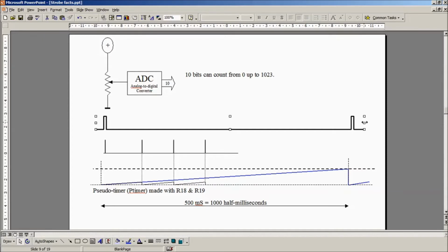When this waveform here is running at a much higher speed to stop a much faster rotating disk, the distance between the pulses is much shorter, and the pulse length itself is much less as well. And I've drawn a representation of that down here. These pulses here, that's this running at a higher speed. Now, the way we make it run at a higher speed is we move this pot. So it might be down there, let's say.